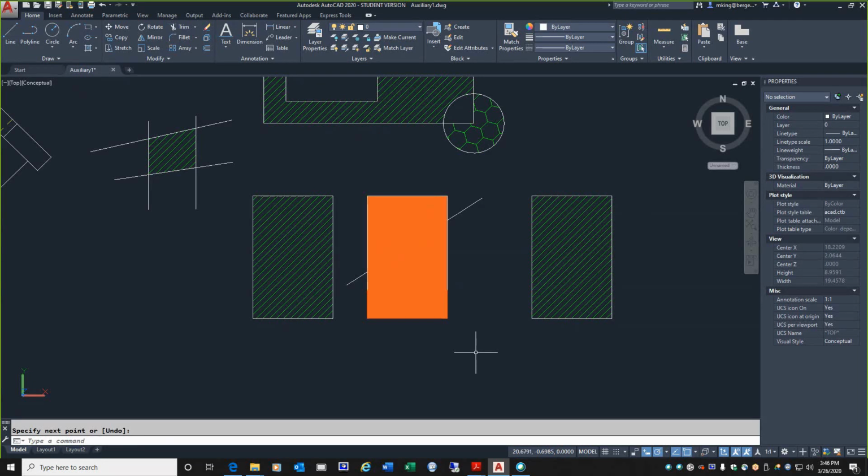Now the strange thing is, I'm not sure I could say that for all of you. A couple of you might be seeing the line, a couple of you don't. And if you look at my screen, strangely enough, the outline shows up to here, but not in my lower portion. This is classic hatch, and it'll play tricks with you and sometimes make you crazy, but we just have to outsmart it, right? And that'll be some of the challenge.